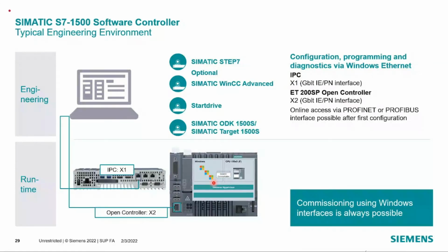So in this IPC, you can install the STEP 7 package also, and the STEP 7 package will have engineering as well. So you don't require any separate engineering package to work on the soft controller and do the PLC programming. On the same IPC, you can install even the STEP 7 package. So now you can see in the same IPC, you have engineering packages like STEP 7 and the WinCC HMI package.